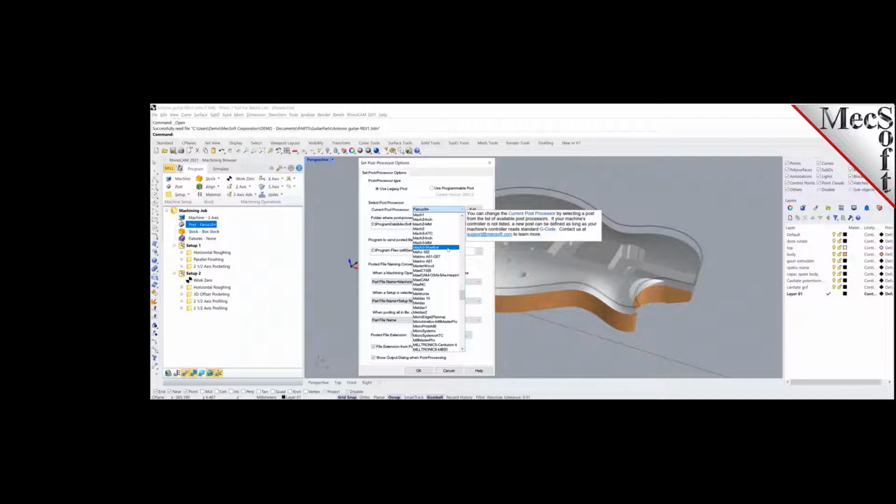You're using inches rather than millimeters. You're in the U.S., so you're probably using inches. Yeah, we actually do both, but you can just do it in inches. Okay, all right. I'll select the Mach 3. And then there are some additional controls to help you in the post-processing. What's the type of file name that you want when you post-process? What is the order and things like that? And then the extension of the file. All of that you can set up here.